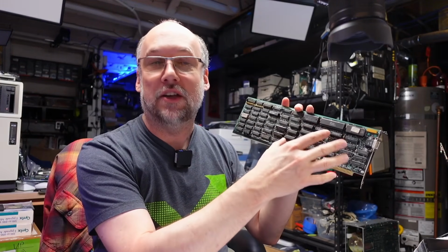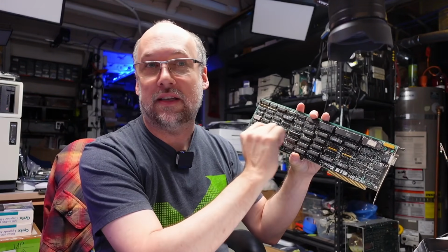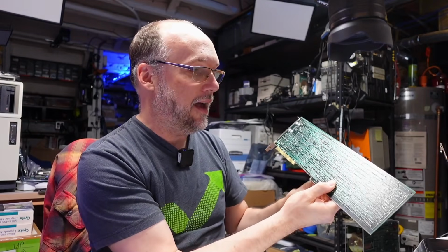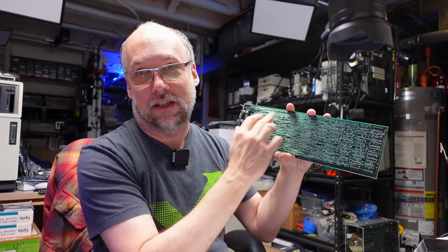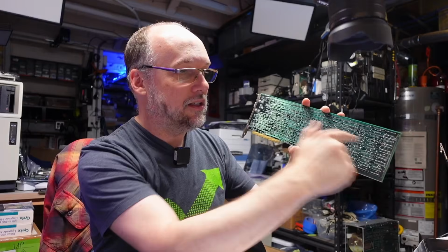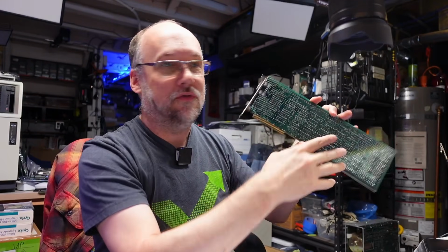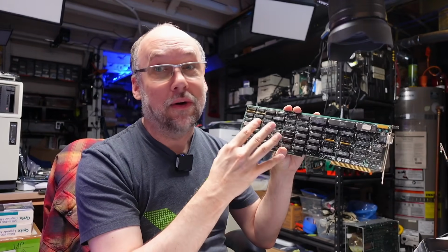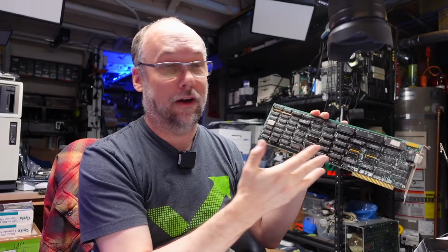And that's one of the issues when you don't have them, is you have to kind of reverse engineer and spend a lot of time tracing out and trying to figure out where the traces go. And on boards like this, it's really hard because it's very tightly packed in there. And the traces make their way all over the board, and they go through vias, and they're underneath all these chips. So there's no real way to do it visually. You actually have to use that brush I was using to try to figure out where the traces go.